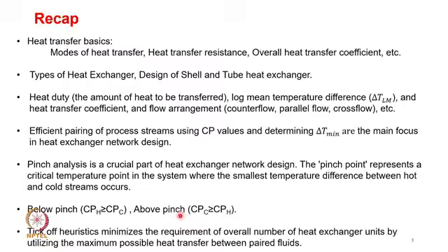Finally, we went ahead and did pairing of hot streams and cold streams by means of tick-off heuristics. Tick-off heuristics help you minimize the total number of heat exchanger units by utilizing the maximum possible heat transfer between paired fluids. They help you connect the process streams that lead to maximum heat recovery. So once that is done, a process design of heat exchangers can be completed.